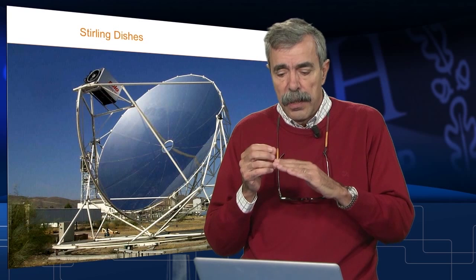But obviously, dust accumulation is going to reduce that efficiency. We have measured that in Spain, for instance, in the south of Spain, we drop something like 6% per week. So we try to maintain the whole system very, very clean to maintain the efficiency of the system.